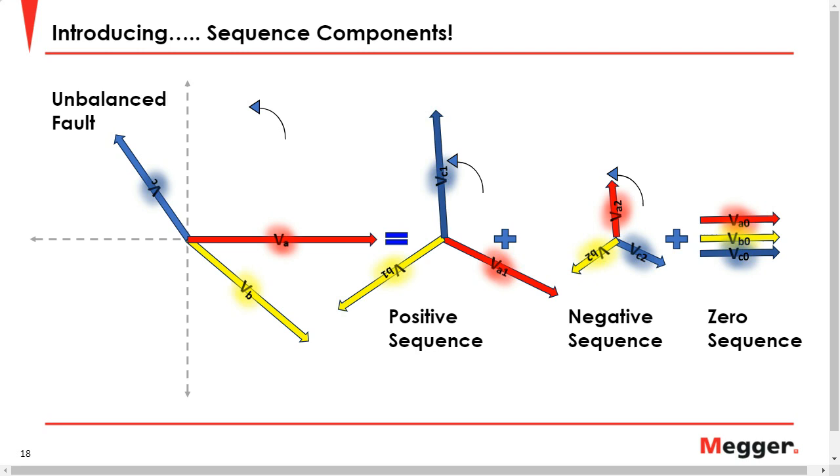So how much negative sequence is there as a percentage of the primary system current, the I1, the normal system currents. So it's not always going to be set in just pure I2 equals this, and then I trip.